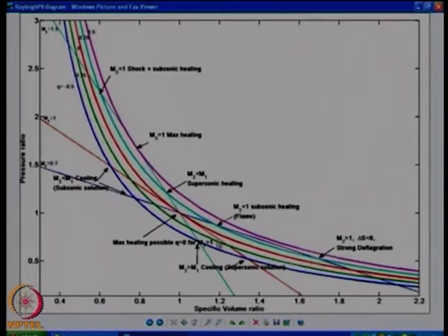these kind of things will not be possible. Okay. There will be a point where I can keep on heating, and I will go to a point between this curve and the next curve, there is a particular Q value for which this is tangential to it. That is the maximum heat I can add to this system starting from a subsonic condition. Okay. That is beyond that there is no solution. If I add a heat higher than that for this magenta curve, I find that there is no solution possible. Okay. That is, the system has reached its maximum T naught star and it cannot accept any more heat, it has gone to that particular stage. Okay. Now we discussed this particular subsonic initial conditions curve for now.